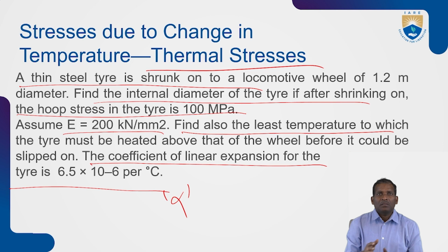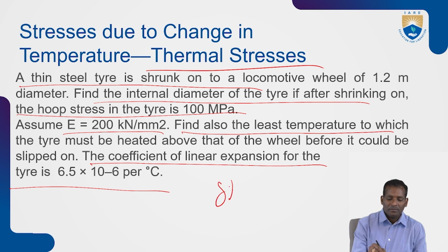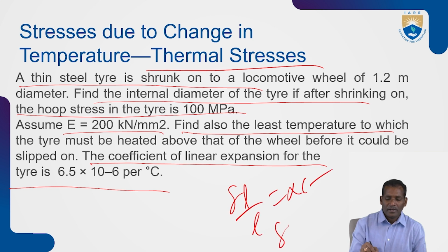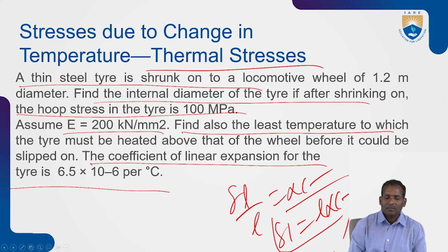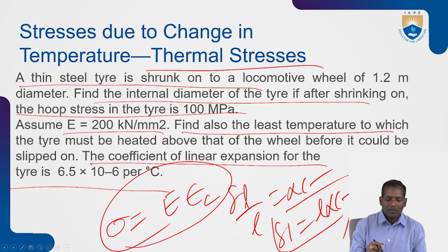So this type of problem is solved by using thermal stress relations. Already you know the thermal stress relation: delta L by L is equal to alpha T, or delta L is equal to L into alpha T. And thermal stress is equal to E into thermal strain.